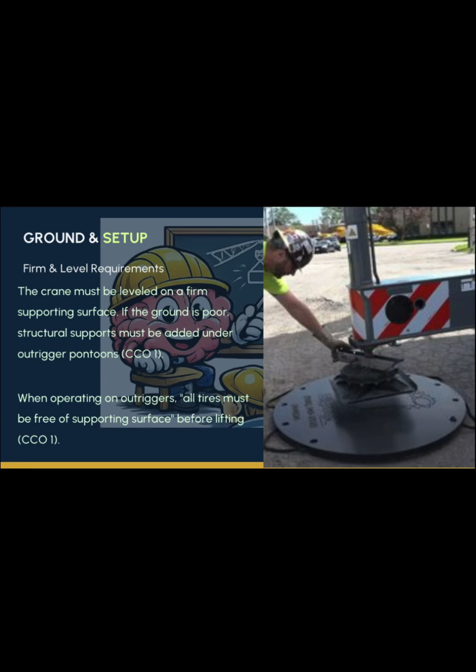All right, here are the fundamental rules that you have to follow for TLL. All cranes have their own specific rules. When the measurement or the radius is between listed values, always use the rating for the next longer radius, to ensure a conservative capacity. We always err towards the worst case scenario.